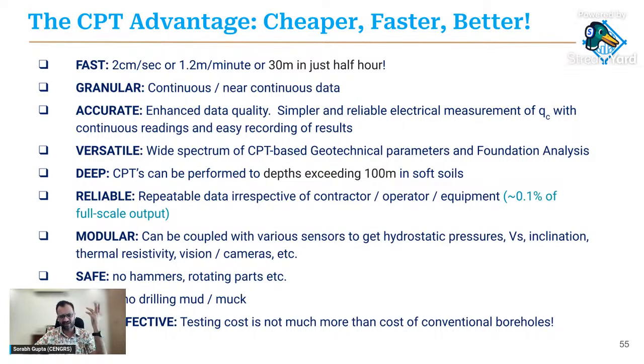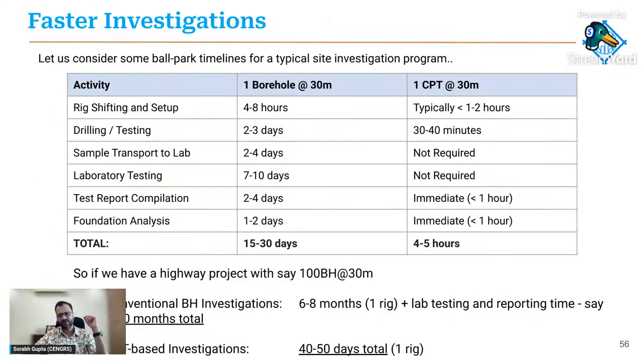Safe, it's clean, and now this is the tricky part. It's also cost effective. So the cost of CPTs, at least the way we are retailing CPTs nowadays, is roughly the same as the cost of conventional boreholes. I think the largest hesitation in adopting CPTs was cost, and we are trying to eliminate that, because now we are doing CPTs at roughly the same cost as boreholes.